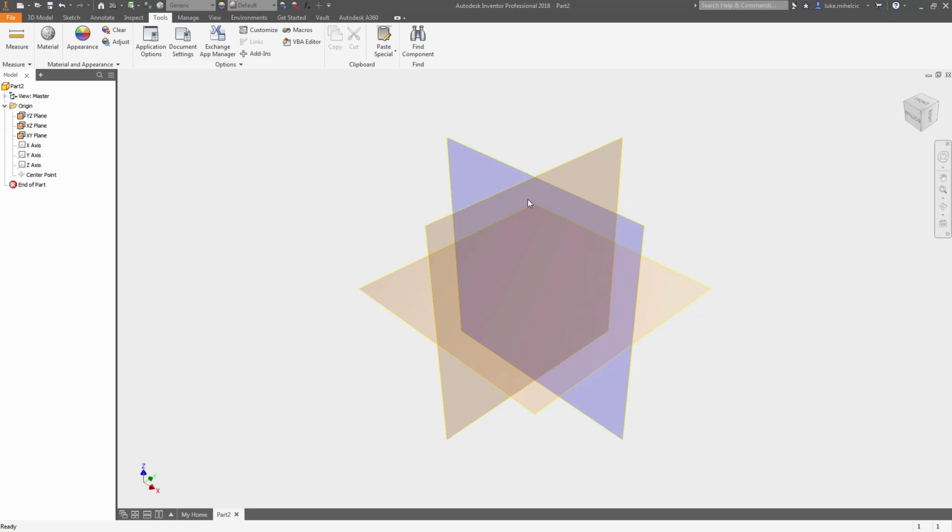Whatever your issue might be, if there isn't a logical 0, 0, 0 point, pick a point that is the most logical, wherever you can find it. Maybe it's a bolted connection where this piece then connects to something else. Make that your 0, 0. That way when you bring it into the assembly, it has a nice location and connection point for insertion.